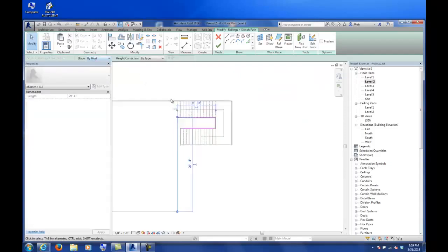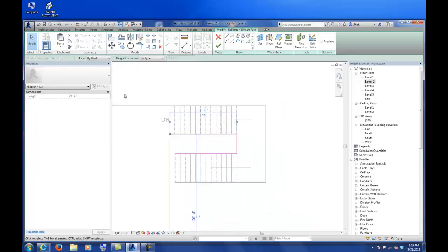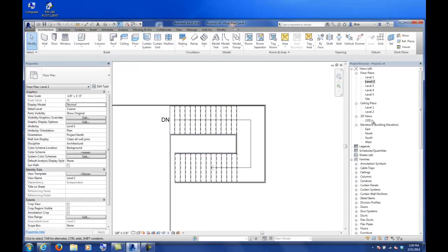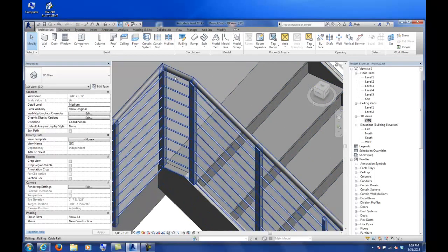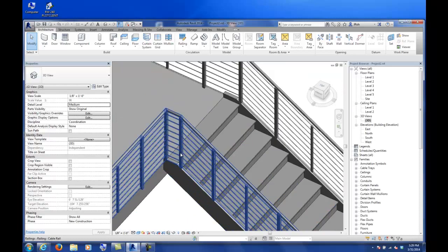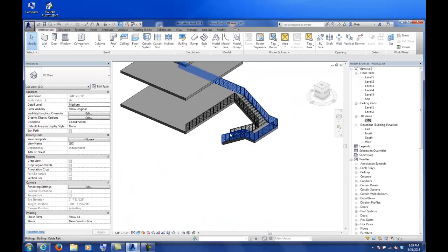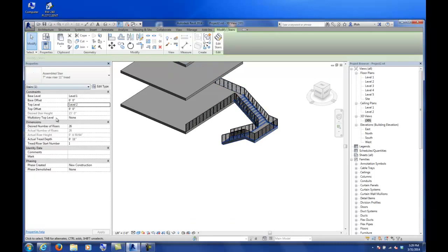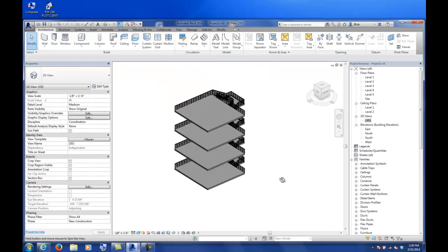And I'm going to also make, any kind of additional lines that you make that aren't part of the stair, you want to make sure that that slope is equal to a flat component. So now you've got that where that clearly connects together and makes the corner post, and then continues on. So again, I could click on this stair, and we'll do this multi-story. And it'll go ahead and complete all those as we go up.